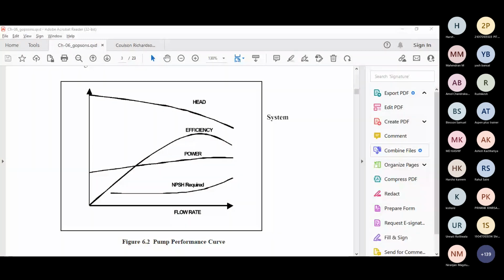But before this, in the discussion about the case of mercury, you were saying that the head of the pump will change. So what is correct? Actually, the head of the pump will not change with respect to density. What I am saying is that your pump will not be able to pump it out. Suppose 10 meter head is the rated head of a pump, and if I am pumping mercury, then your pump will not be able to pump it out. See, density has nothing to do with the head of the pump. It is linked with the power.